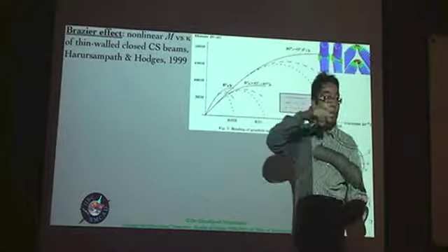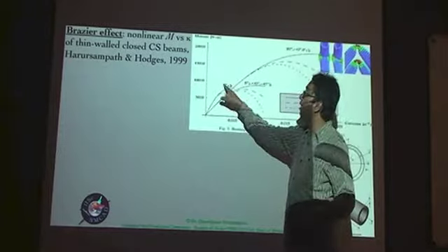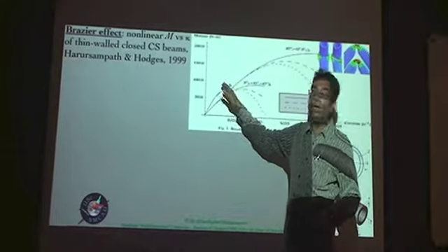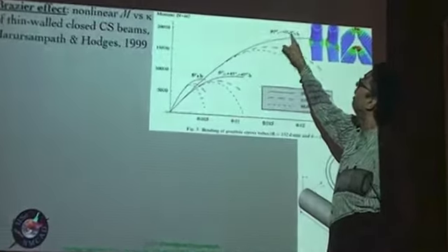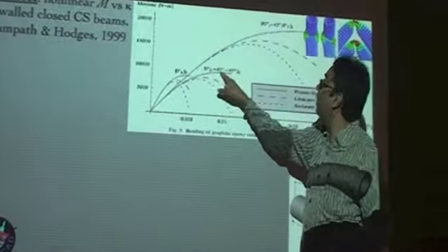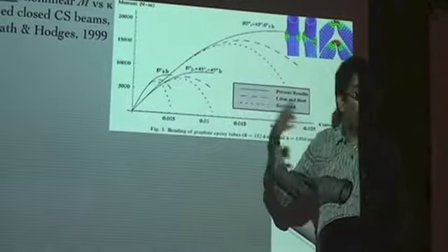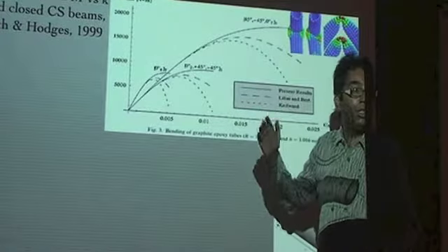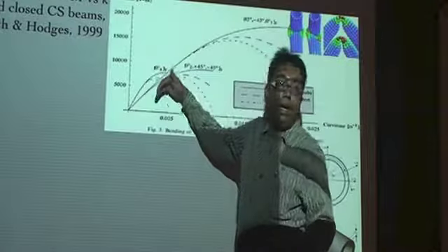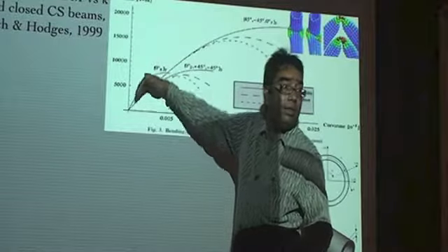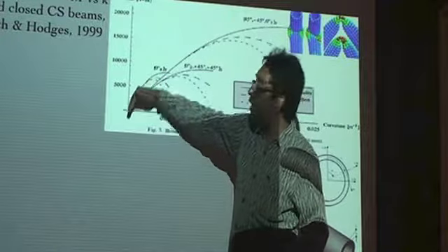So these are all for composite structures. So for example, you have unidirectional 0 degree plies, just 8 plies. Then you have different types of other layups, 45 minus 45 0 or 0 plus 45 minus 45 for the same composite material, same volume fraction, same fiber and same matrix. So depending upon the actual layup, you will have different stiffnesses which are there initially.